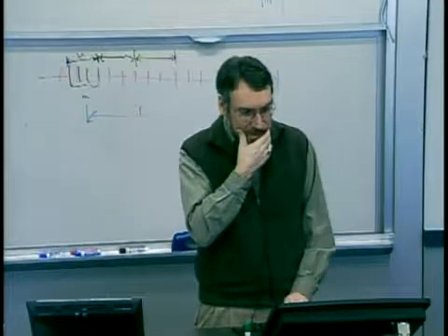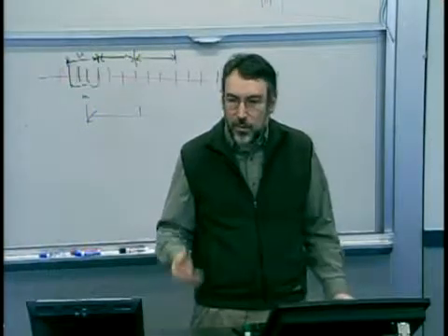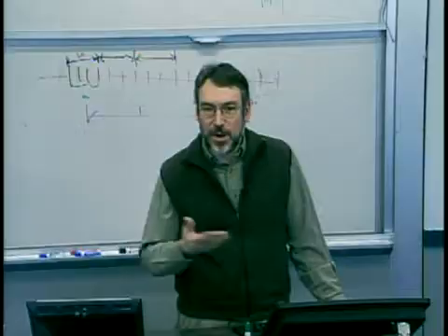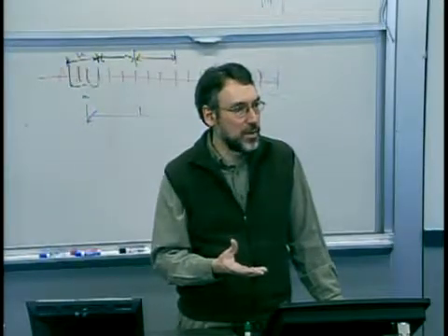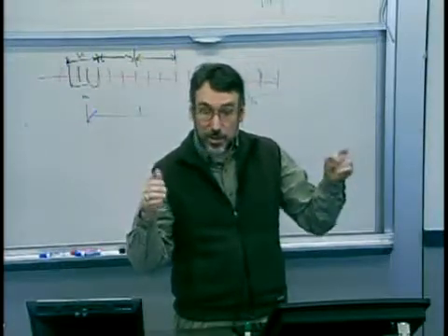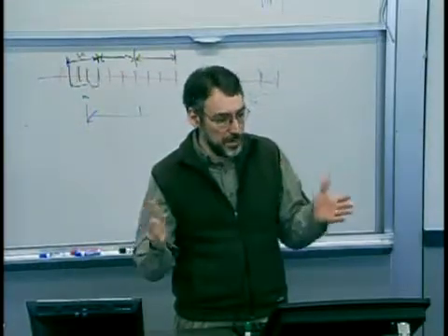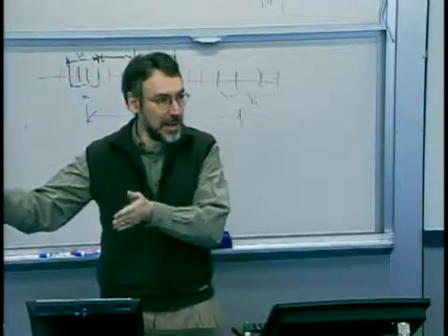Okay, so just to recap a little bit on the process capability, what you've got is some characterization. You've got a model of your real process, where it's really operating when in control, in the best situation. You know its mean, you know its variance. You've got the requirements, the spec limits.